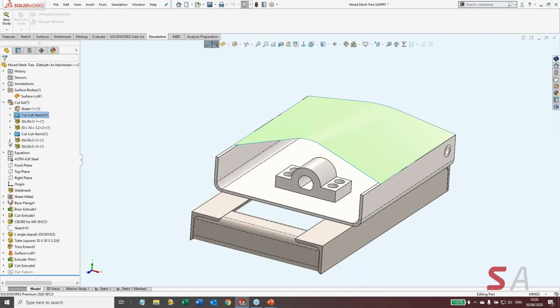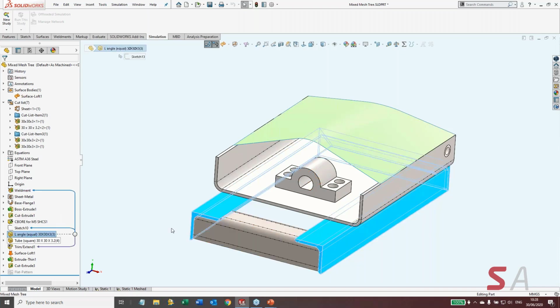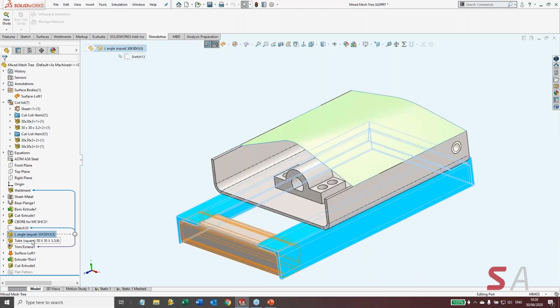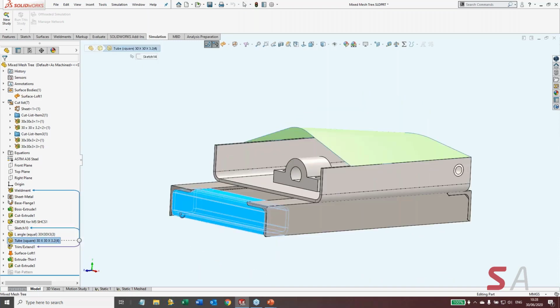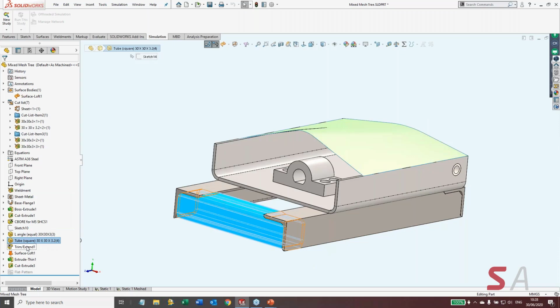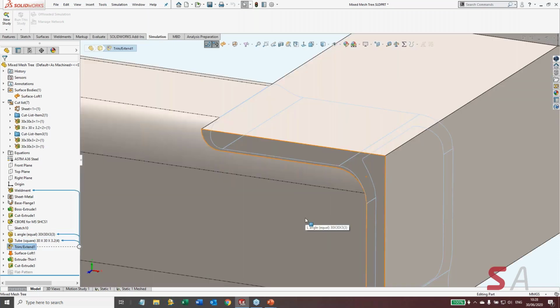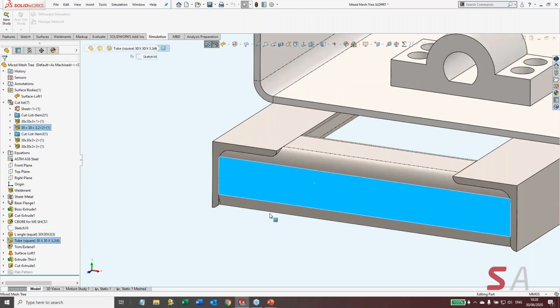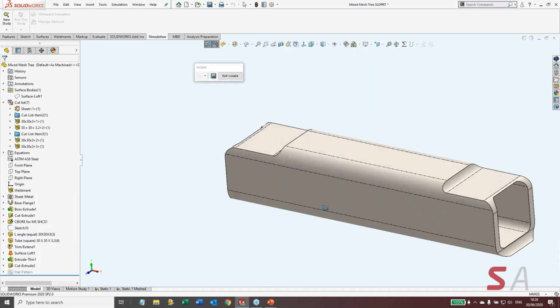I've done a couple of weldment items. You see there's a weldment feature. There is an L angle feature with 3 L angles in it. And then there is a square tube, and I trimmed that square tube to the L angle bodies. So that's where this trimming comes in there, right? So you can see what that guy looks like on his own. If I isolate, all right.